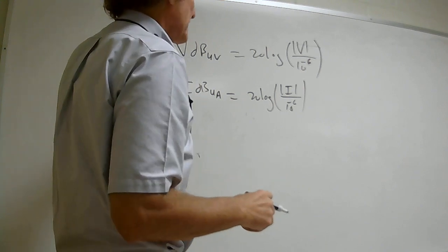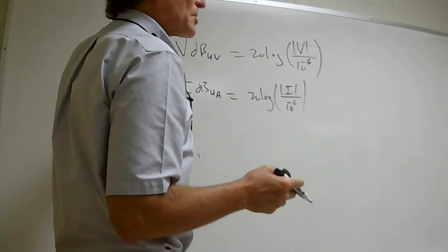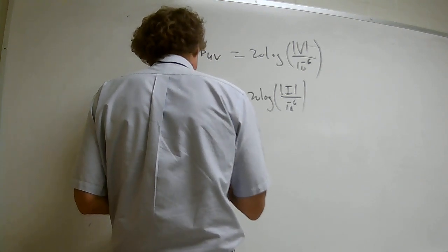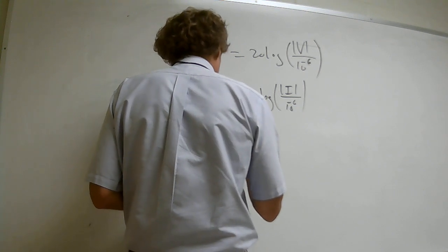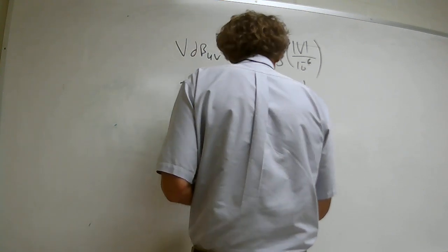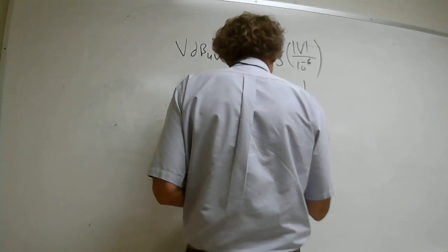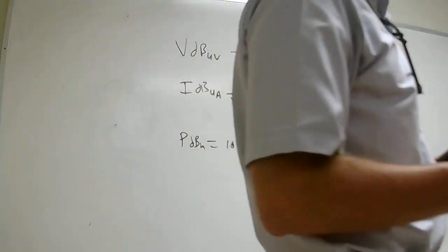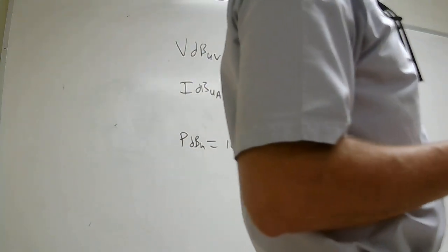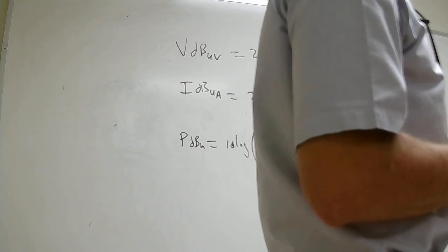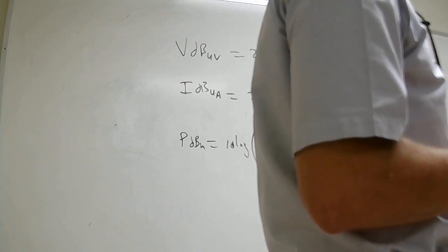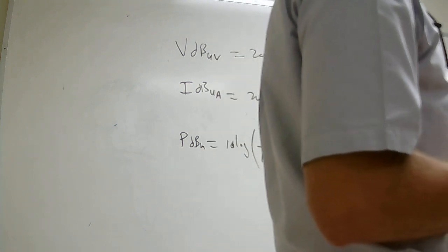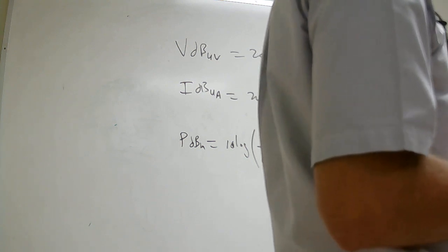These units are standard. When I teach EMC and in radar, we use these commonly. And then with power, power is in dBm. That's milliwatts. And it's 10 times the log of the power, really power over 10 to the minus third watts. Now, have you heard of dBm? If you have phones, you can look up, I believe, your cell phone, the nearest tower's power being received at your phone in dBm. If you have one, you can try it. When I do EMC and radar, I have people do this because it's extremely low.